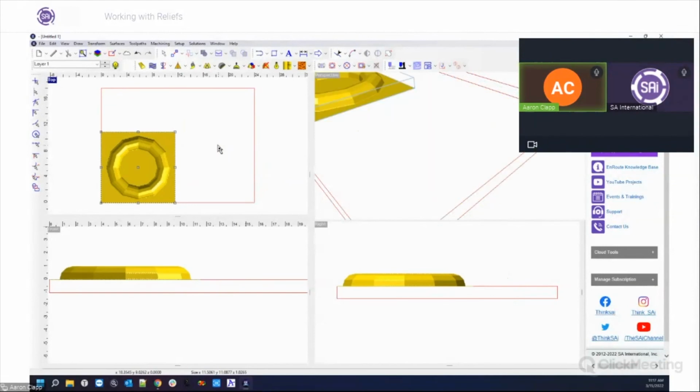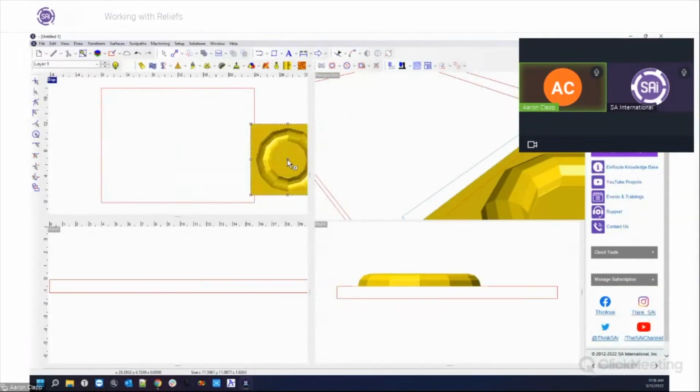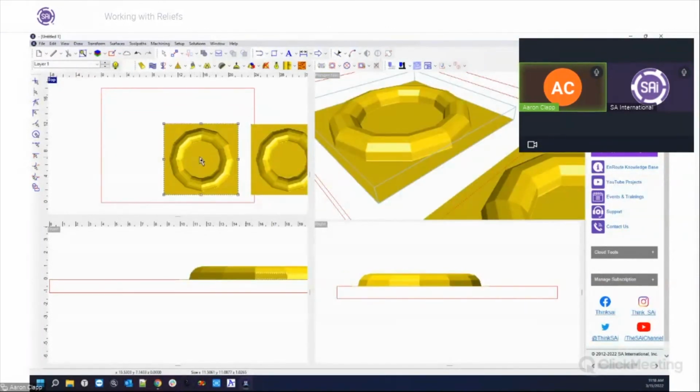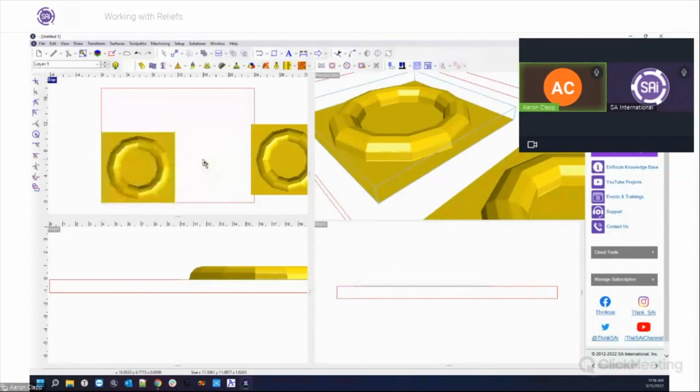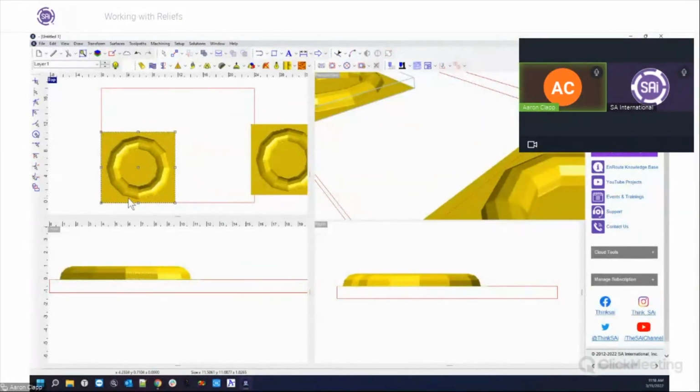And then what you could do is line up your part into a corner, for example. You would have to set up some kind of jig or some kind of setup where you confine the piece so that when you flip it over, it puts it exactly in the same location. That might be dowel pins, or maybe you screw something into the spoil board so that you can shove it into the exact same spot where it was. And then you'd cut the top, flip it, move this piece out of the way, bring your other piece that had been chamfered for the other side, put it in the exact same location, and then run the cut again.